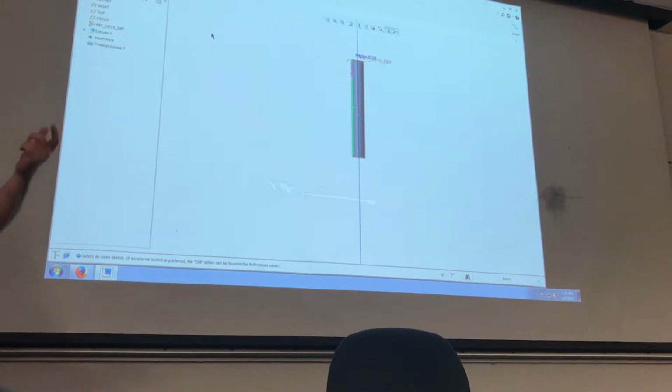The places where you see left-handed threads is in power transmission devices where it has a nut on it, such that the driving force tightens that nut down even more, rather than loosening it back up. But most of the time, you're going to see right-handed threads. Things like turnbuckles, where you take a center section and you rotate that center section, it'll have a right and left-handed thread so it can open and close the sides together.